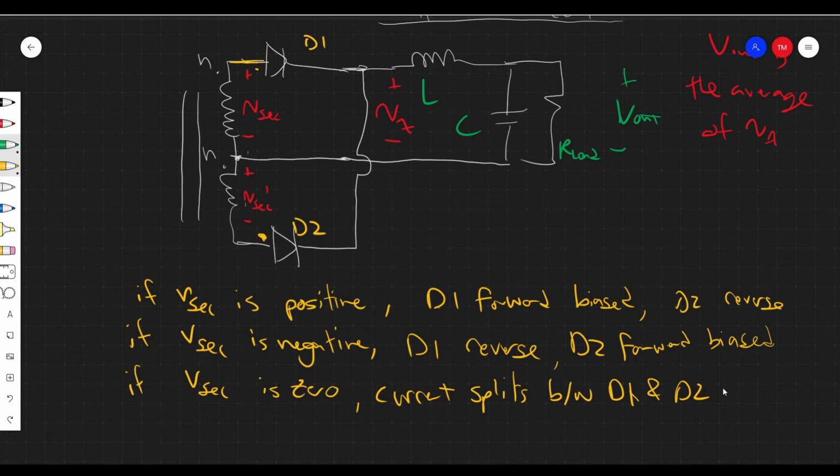And that kind of matches up with the way we're controlling the primary side, right? We have three states typically with the primary side. One state there's a positive voltage, one state there's a negative voltage, and one state there's a 0 voltage. So the 0 voltage state is really very important to understanding how this works because it creates this synchronous rectification state that we have in the buck, right? Where we provide 0 volts to V out and allow control over the output voltage, right? The length of time that we have a positive voltage compared to the length of time that we have 0 voltage actually is what controls V out, right?